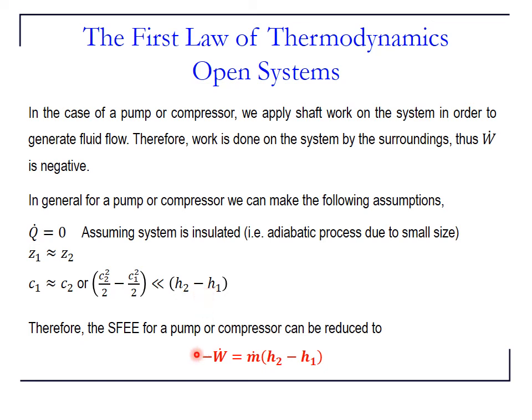Therefore, finally, we get this equation. Q is 0, so Q has been cancelled. You have minus work transfer left on the left-hand side, and this is m dot times the difference in enthalpy between the inlet and the outlet.